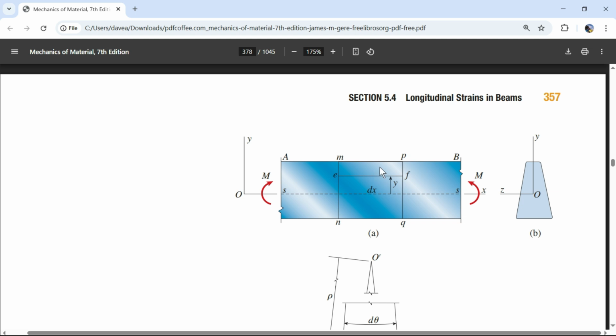So as we are visibly changing the length, if there was no bulging, that would just be a new volume. Like we're literally decreasing the volume. Poisson's ratio says that it doesn't decrease that exact amount. Some of it, about 30%, gets pushed out the sides. You know, for steel it's 0.3.